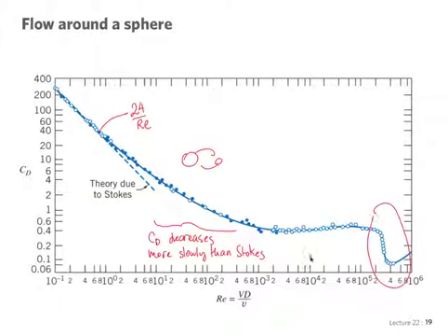In this case over here, look at this. There's a very important thing that happens there, which is there's a sudden reduction of the drag coefficient due to the fact that the boundary layer in the front of the sphere becomes turbulent. The momentum flux is higher. The particles are able to go around the sphere a little further to the back, and this delays separation.